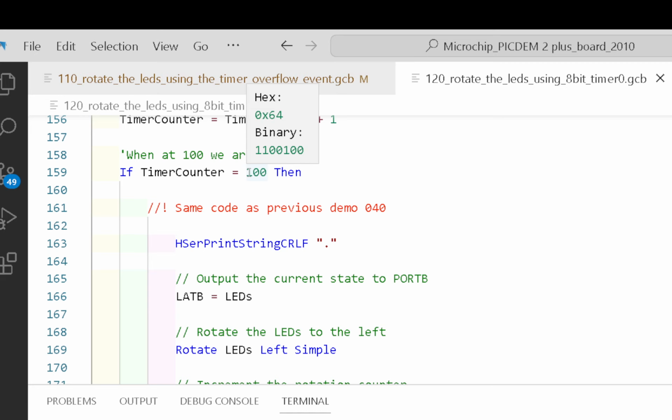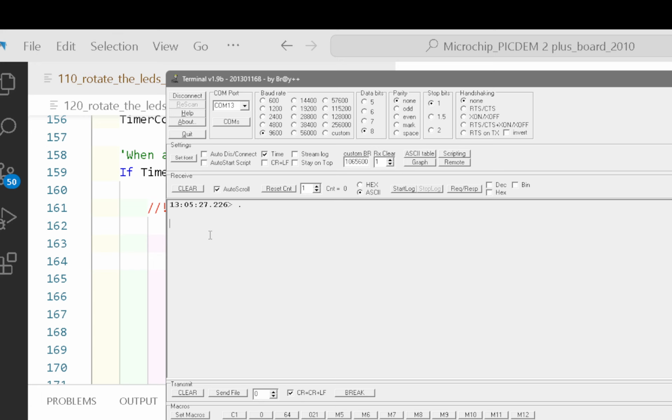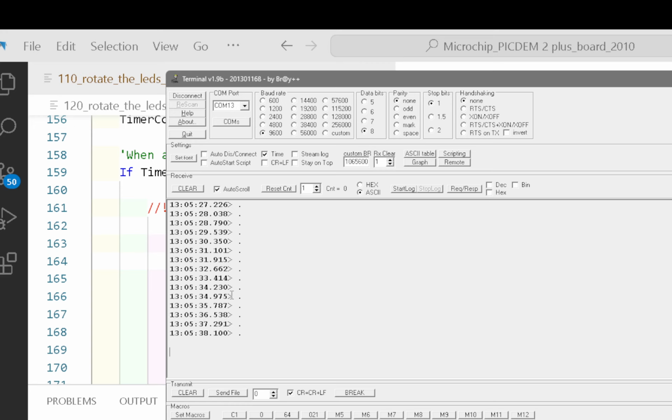I would imagine I've chosen 87 because of empirical testing. What I mean by that is, we'll have a look at the terminal to see what's happening. This is the terminal, clear that down. I have programmed it. Yeah, I'm still using the internal clock and it's not accurate enough. If I did this on a 31 kilohertz clock, it would be very accurate, but it's approximately 1 second. Look. And I think that 87 was okay when it was a bit warmer in here.